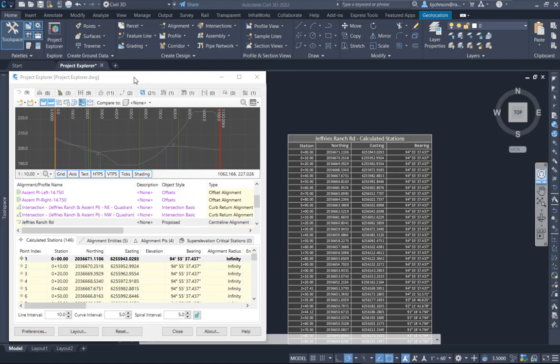During the course of our projects, we often find that there's a need to share one of the Civil 3D objects with someone that has AutoCAD. Something like a surface that they just want to have the contours from. Project Explorer has a solution just for this purpose. It provides functionality to export specific Civil 3D objects to a drawing file that can be opened in any application that supports the DWG file type. The exported Civil 3D model results in 2D entities representing an object in plan view.